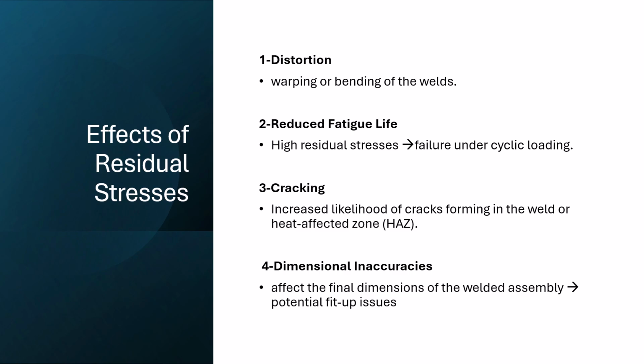It might cause cracking, especially in the heat affected zone, or dimensional inaccuracies, which affect the final dimension of the weld assembly, and we have fit up issues and we have to do the weld again.